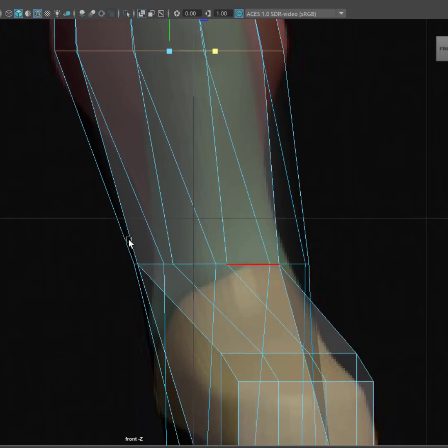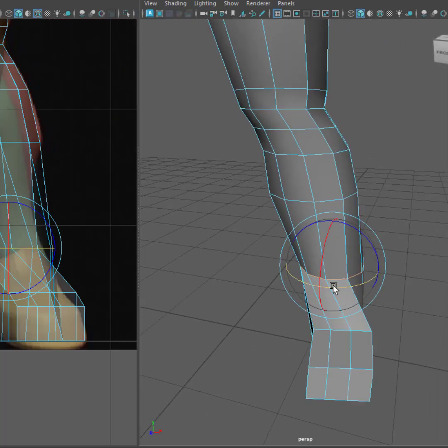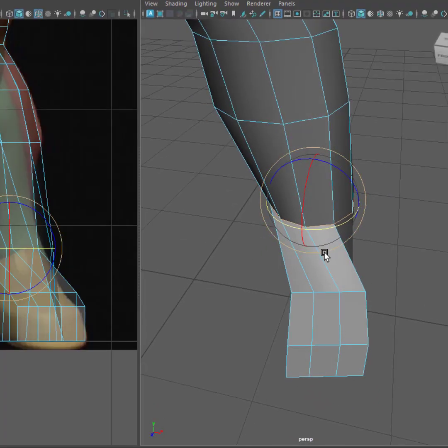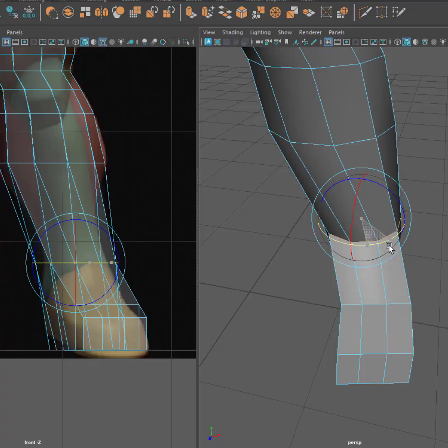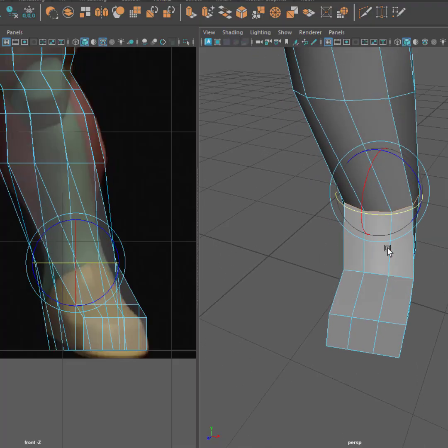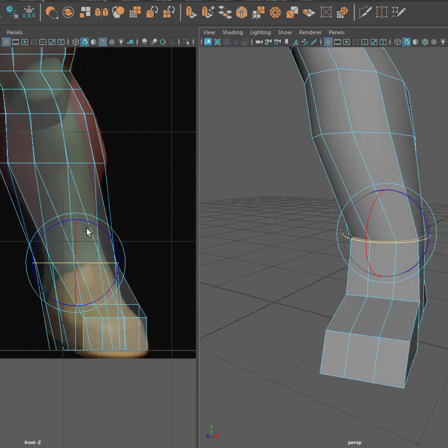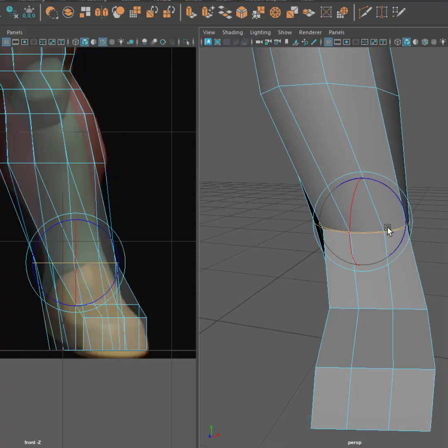And then here, again, I will select those edges. I'll deselect the ones that are standing or slanted. And then I'll press E. Spacebar, I will look here at the perspective because right now it is twisting. I'll twist it outward like this. Yeah. So this has a different flow. So I want it straightening out of the foot. That's my concern, not yet on the legs. So that's how I manage the flow of this.